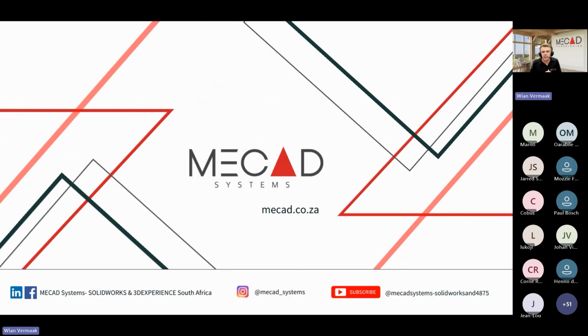So Fiddly asking, does drawing automation let you choose the type of dimensioning you want? The type of dimensioning is actually very easy to change. This is absolutely based on your template. So where we choose your template, whatever settings are in that template is going to be used inside of all of your drawings. So it's just exactly like starting a new drawing and then dragging all of your views in, dimensioning, all those repetitive steps. We're just taking that template, doing everything for you in record speed, by the way.